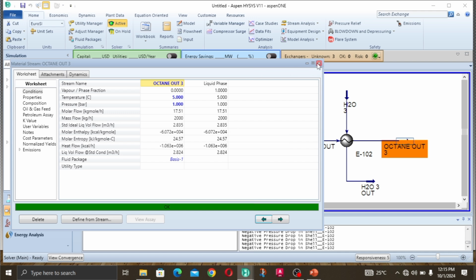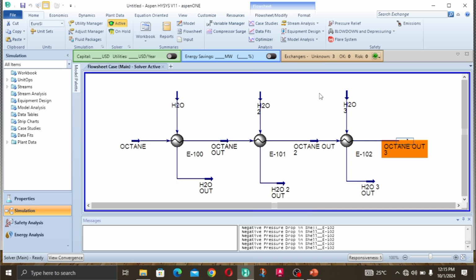With that, Basaka has achieved cooling, and Mary's frozen soups have achieved heating. And this here is the concept of heat exchanging using a heat exchanger train. And it is nothing more than heat exchangers optimization. Instead of using 3 heaters and 3 coolers, you just use 3 heat exchangers to do heating and cooling simultaneously. Saves time, cost, utility, resources. Very convenient, a very beautiful thing in process engineering operations.